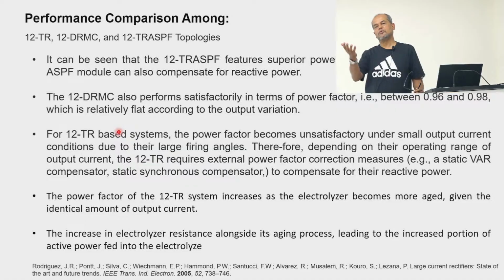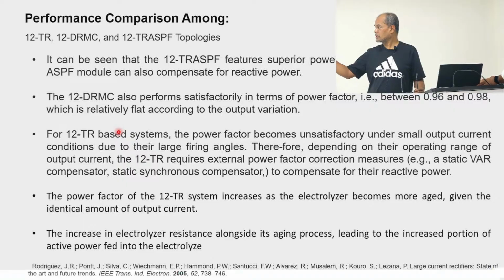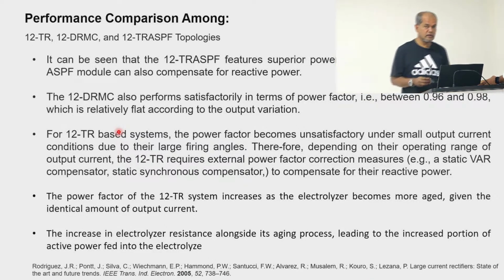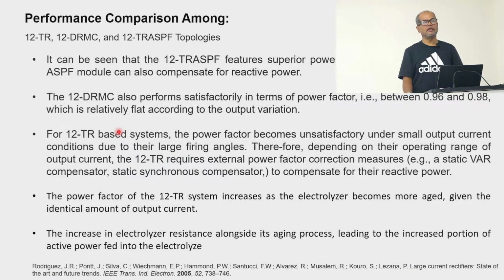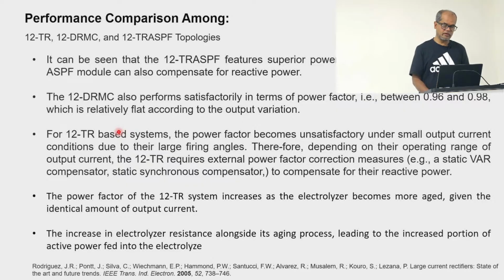For example, people use shunt capacitors. People can also use FACTS devices, like static var compensator, which is called SVC, and also other components called static synchronous compensator, which is called STATCOM. But again, you have to invest to buy those devices. The solution is available in the market, even if you use the thyristor rectifier. But at the end, that's also going to increase the overall cost.